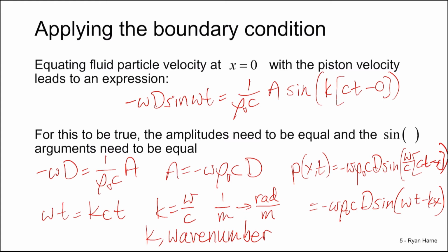What we've just determined is the solution for acoustic waves traveling in a one-dimensional long pipe or duct. These are called plane waves, and in every cross-sectional slice or plane along the axis of propagation, the acoustic variables are constant. We can simplify the solution for plane waves using complex exponentials.